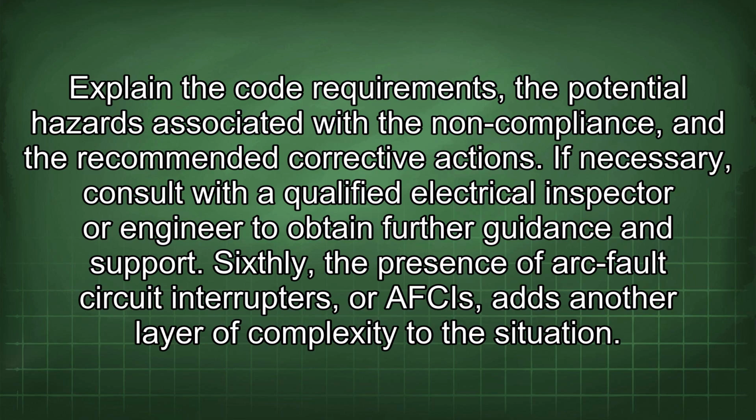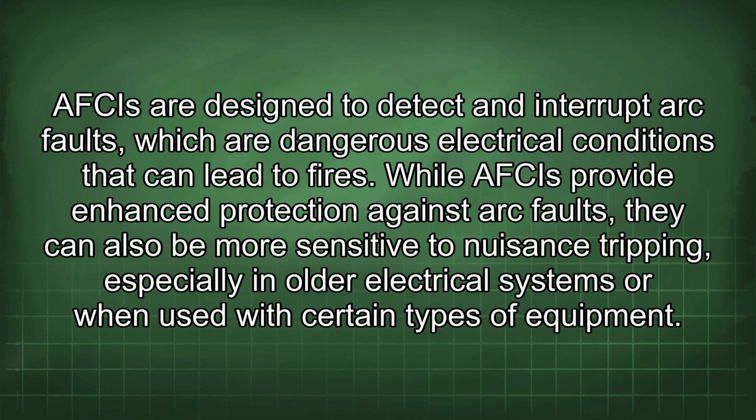Sixthly, the presence of arc fault circuit interrupters, or AFCIs, adds another layer of complexity to the situation. AFCIs are designed to detect and interrupt arc faults, which are dangerous electrical conditions that can lead to fires. While AFCIs provide enhanced protection against arc faults, they can also be more sensitive to nuisance tripping, especially in older electrical systems or when used with certain types of equipment.